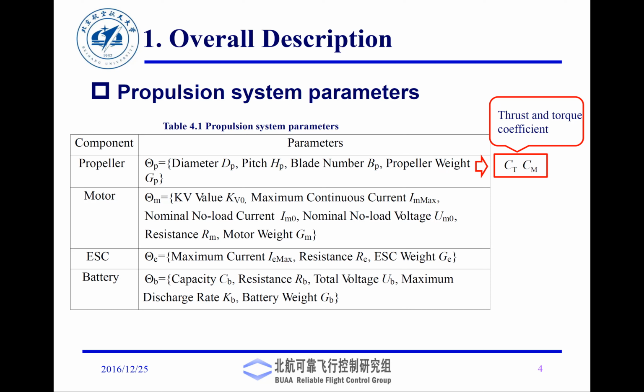Quadcopters can. For the motors, you would have something called the kV value, and for motor design, you are going to use the same principles of circuit design. You would use an inductor, and you would use a resistance, capacitance type of network. It will also have some current specs. The motor will also have a no load current, which is the current the motor is consuming at no load. It will also have the no load voltage. The motor will have its own internal resistance, and it will have some weight.